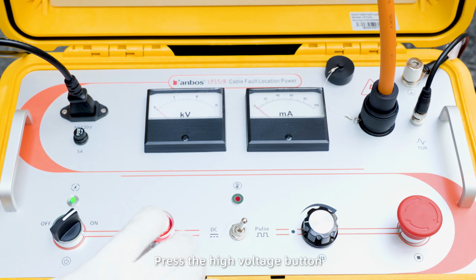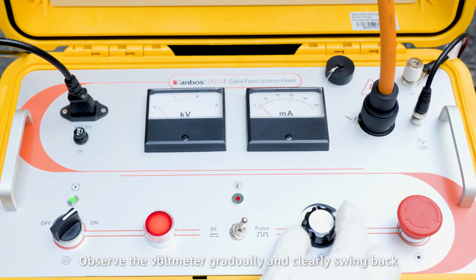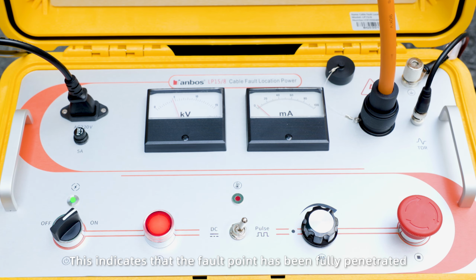Press the high voltage button and turn the voltage adjustment knob clockwise to increase the voltage. Observe the voltmeter gradually swing back. Simultaneously, a crisp discharge sound will be heard from the internal ball gap of the instrument. This indicates that the fault point has been fully penetrated.